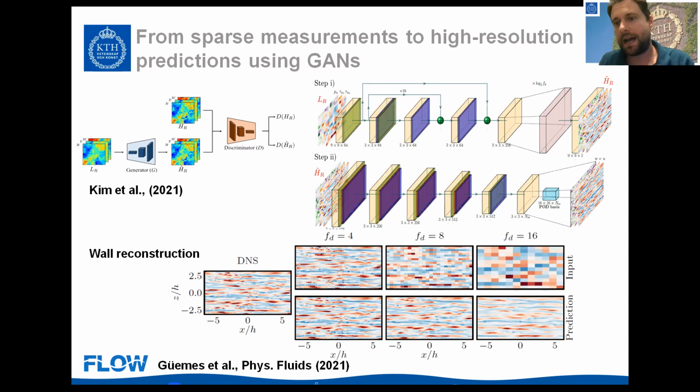Of course, with the camera itself you only measure the temperature, but they can measure the heat flux, resolved in time, and with a resolution in space that is, well, I don't think it's possible to measure directly, just like it's not possible to measure stress directly, only with a model. I don't think there's a direct measurement of heat flux or of stresses. I will check exactly what they do. For the wall shear stress, with hot films you can measure it, but of course there is a model for the hot film, for the sensor that you are using. Right, that's what I mean. There's no direct measurement for stress.